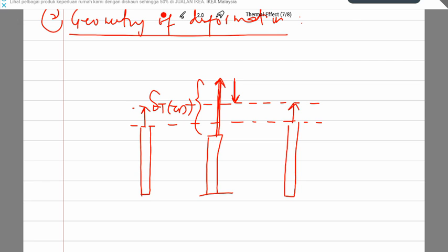So again, this position here is determined by the elongation of these two rods AB and also EF, or the stainless steel rods, and we can say that this is the final position of the bar.